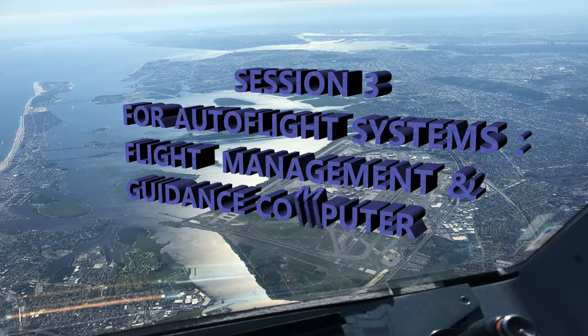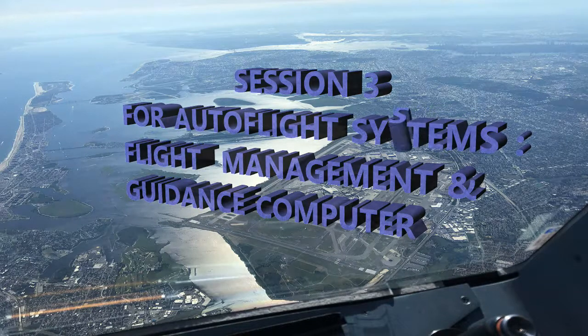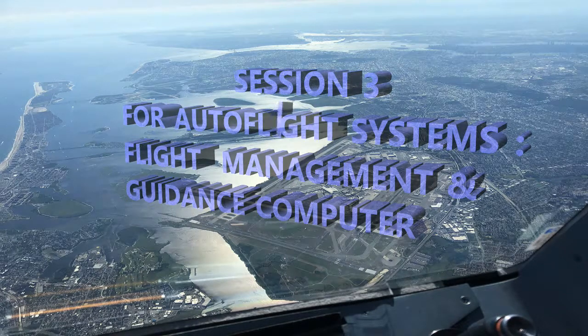The other thing that you have is altitude control. With the altitude selector knob, you've got an outer and an inner knob, almost on top of each other. The outer knob has two selectable positions: 100 feet and 1,000 feet. Then you've got an inner knob that's going to set the altitude in the FCU altitude window with increments, depending on the outer knob position. This knob can be pushed or pulled and turned. If it's turned, it's going to be changing by thousands or hundreds of feet, depending on the outer knob selection.